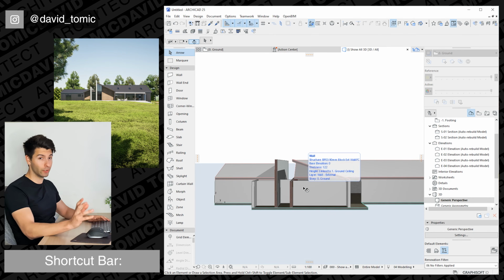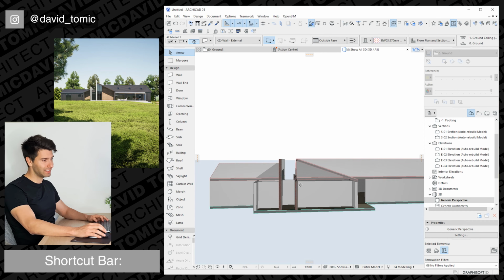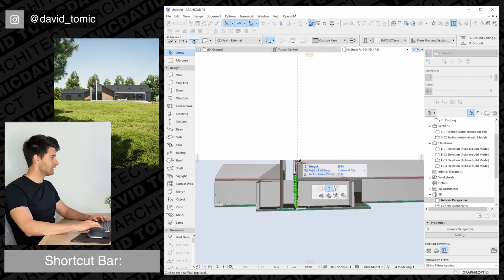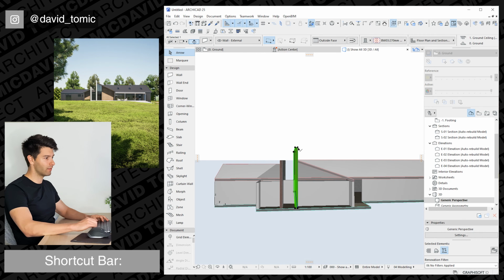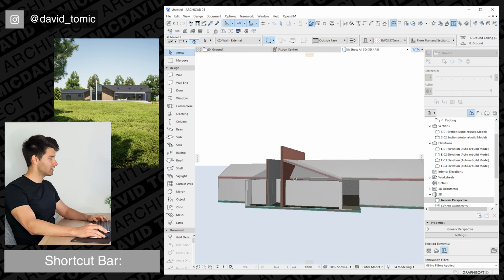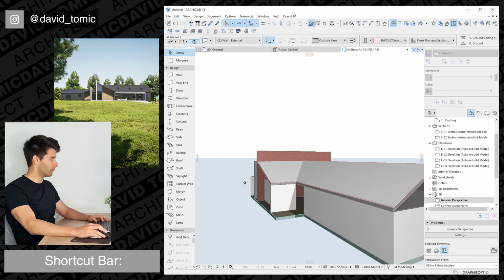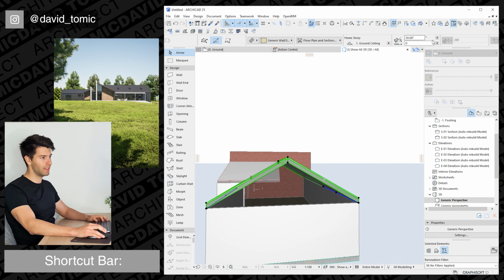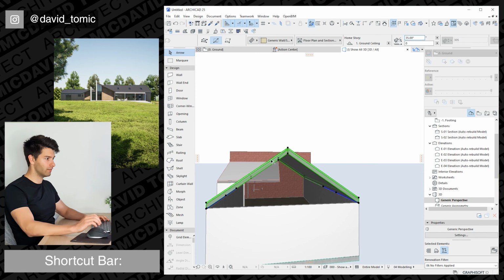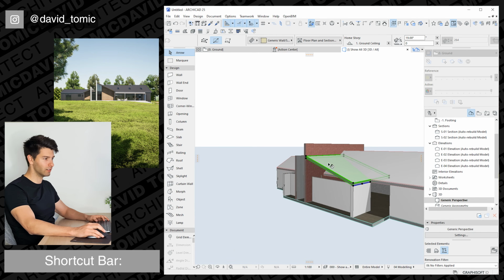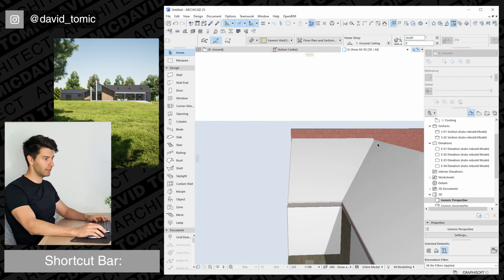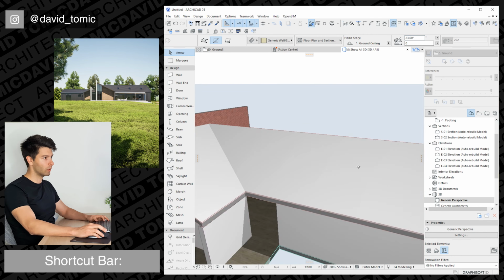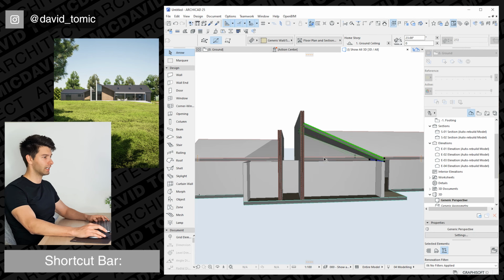Now that that little bit's out of the way, we can select this secondary blade wall, click on this here, and let's bump that up to about 7 meters. I want to extend it just a little bit more than what we had before. I do want to make this slightly higher, so if I select these two, let's go 35 degrees instead of 30 degrees, and then continue to increase this wall on the front of the roof as well to about 23 degrees, so it aligns like it needs to.